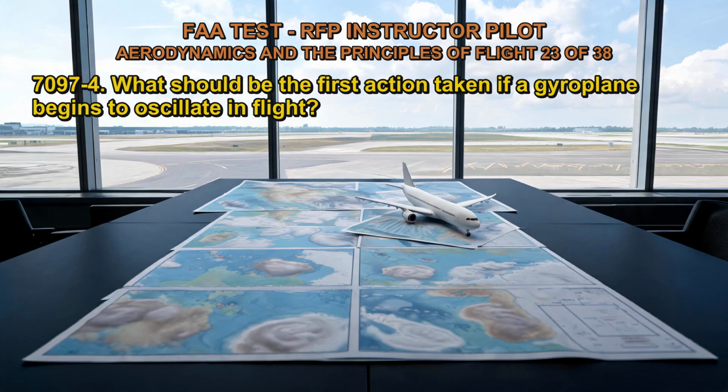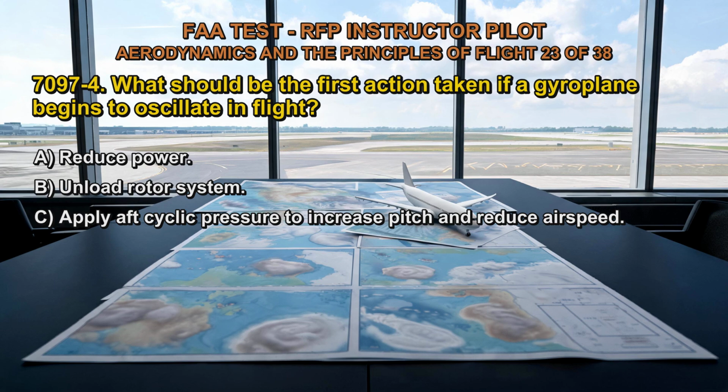Q7097-4. What should be the first action taken if a gyroplane begins to oscillate in flight? A. Reduce power. B. Unload rotor system. C. Apply aft cyclic pressure to increase pitch and reduce airspeed. The correct answer is A.